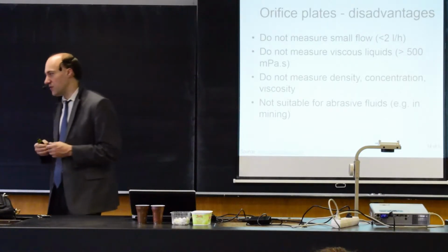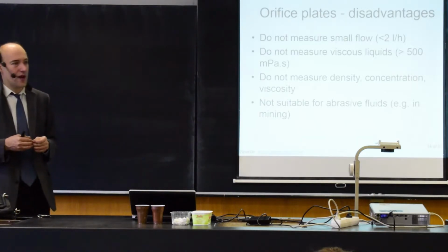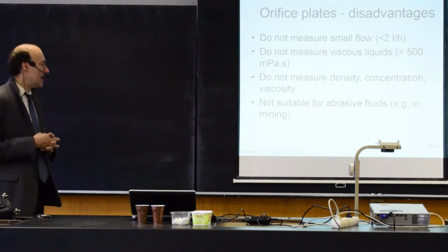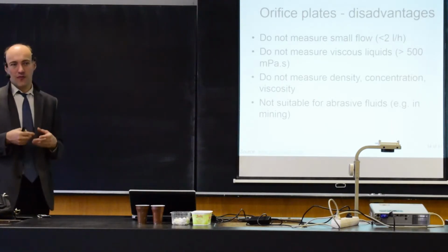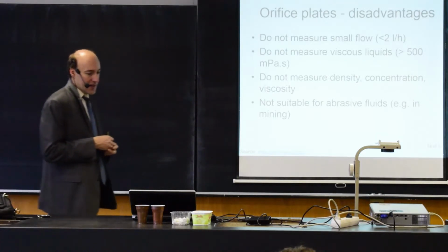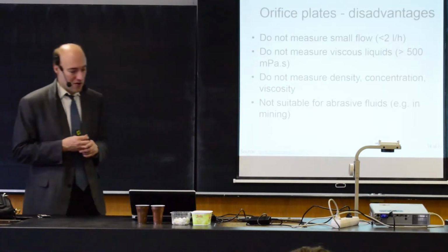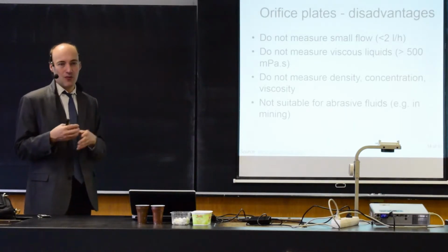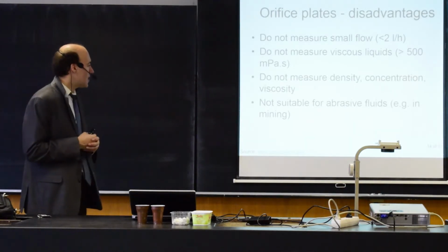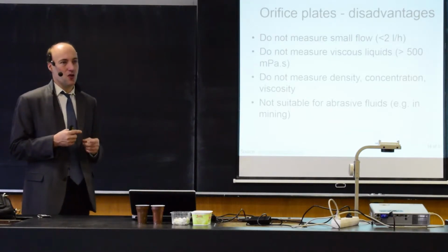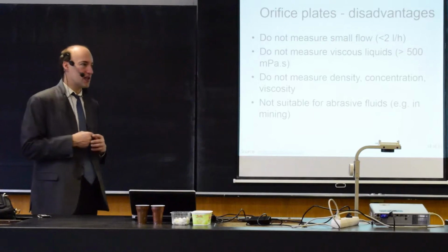It's clear, because if I have a really small flow rate, then I will have a really small pressure difference. So typically it does not work for flows smaller than 2 liters per hour. It does not measure liquids that are really viscous, so if it's like honey or even thicker, then it's not working.